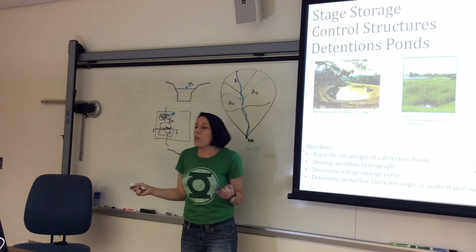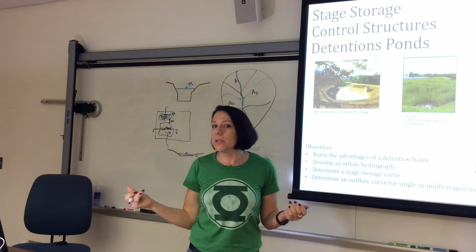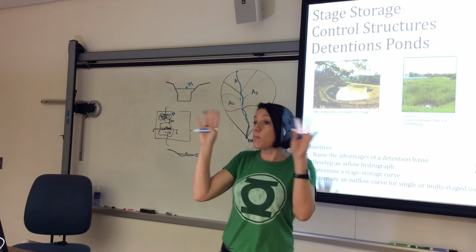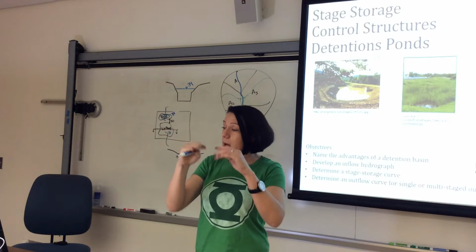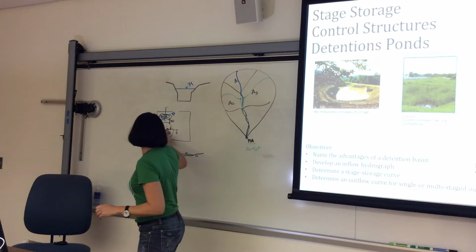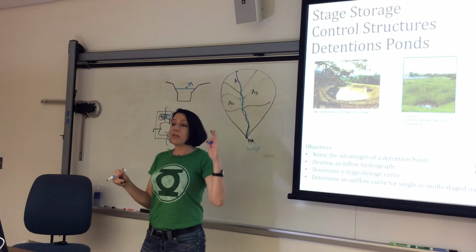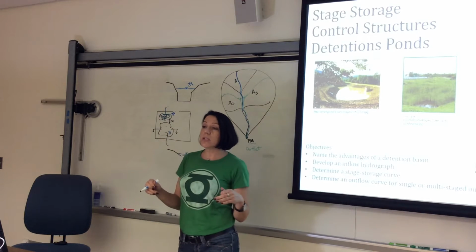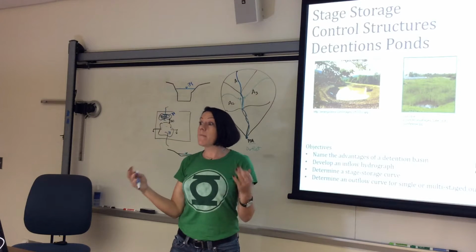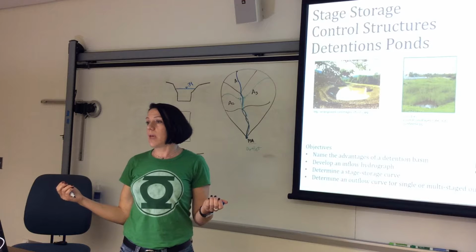Now, how to figure out where the water is, or the normal pool in a wetland, is usually an environmentalist's job. They say there are markers on trees, high water levels. Let's say that's not a wetland, that's just natural ground. So what a soils person, a geotechnical engineer, would do is go out and do borings into the ground, and they would say, okay, where was the groundwater located?